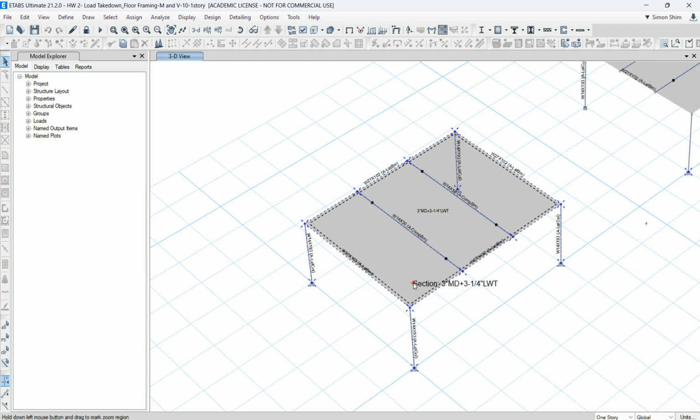Even in a tall building, most likely if you see a connection like this, only web to web, this is a simple connection. It doesn't generate any rotational resistance. So typically our intention is that these beams work like simple beams.